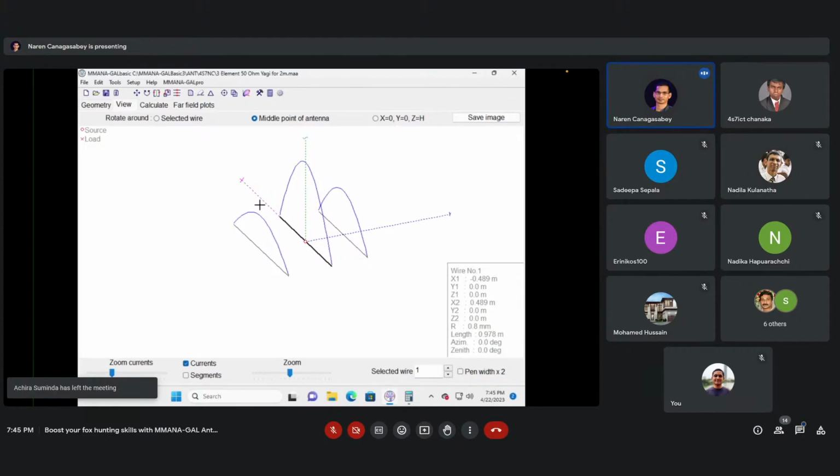So Nabila, this antenna we've designed for 50 ohms direct match. Since you're not going to transmit on this, we can do a direct feed. So the center conductor would go to one of these elements, and the outer wire or the shield would go to the other element.